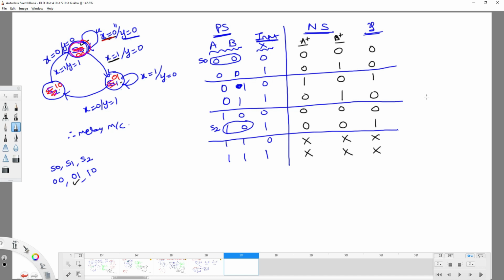So guys, here the point is, you have to follow this particular approach in Mealy machine only. In Mealy machine, if the states are not defined, you have to write them as don't cares. Whereas coming to Moore machine, you should not do like that. You have to just simply leave them as blanks.